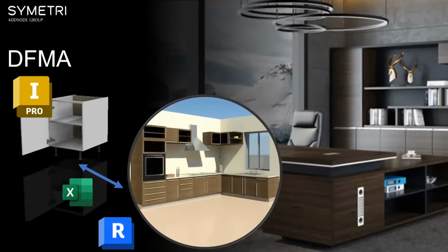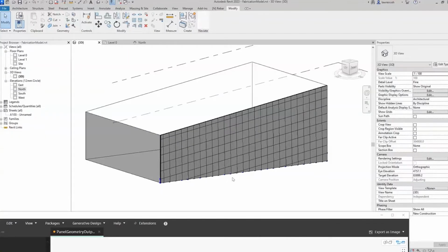So the manufacturing model would, of course, then drive the CNC tools and the routers to obviously cut out all of the individual components, do all of the drilling of all the parts, and also look at things like finishes that people might have requested. So this particular tool here is going to extract all of that information from Revit and automatically create a whole bunch of iParts in Inventor. Okay. Obviously, again, you can see that Excel is our gel between the two Autodesk products. So let's take a look at this.